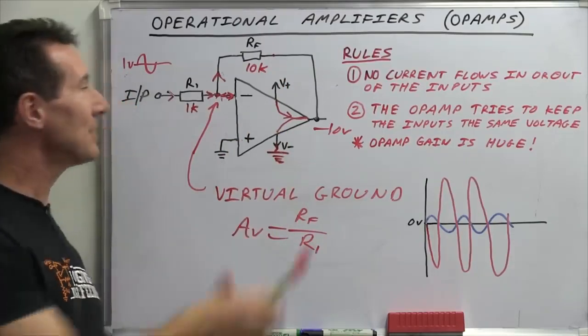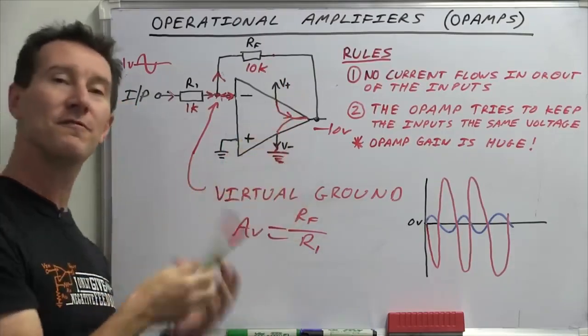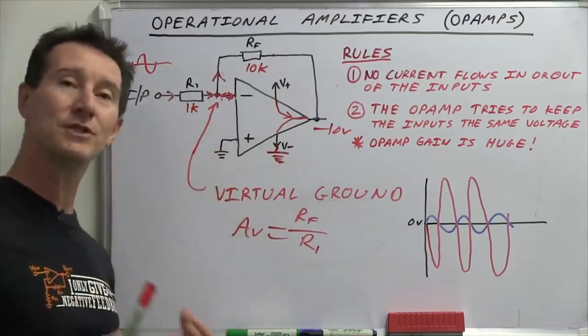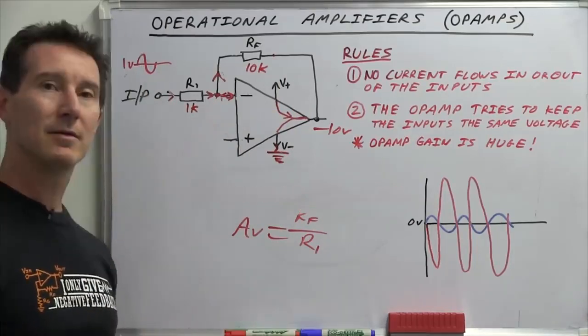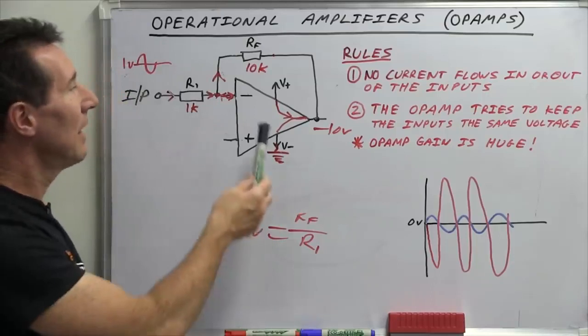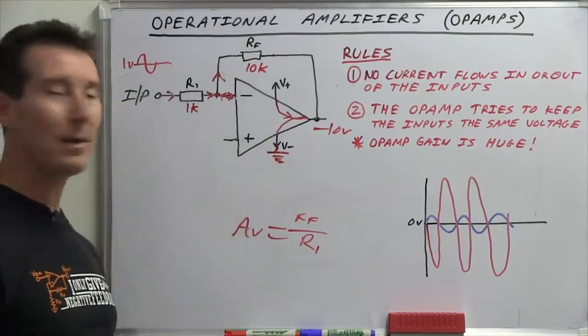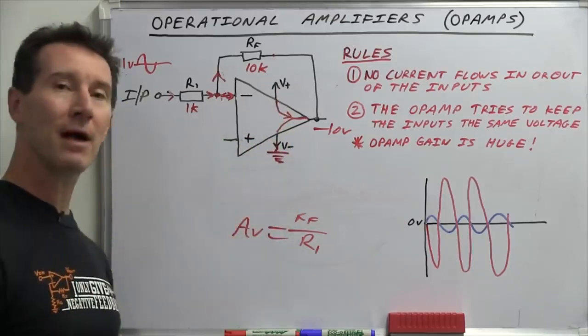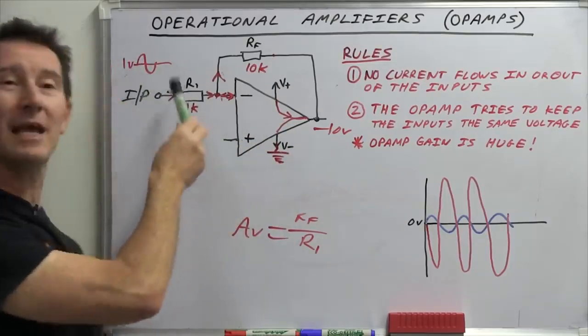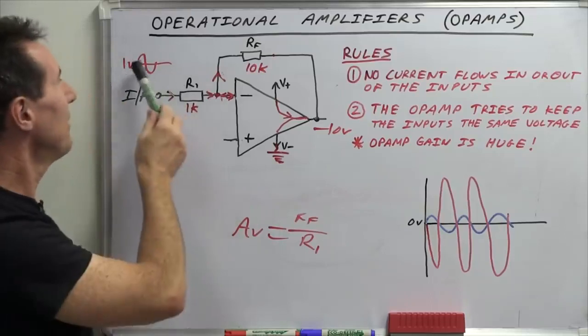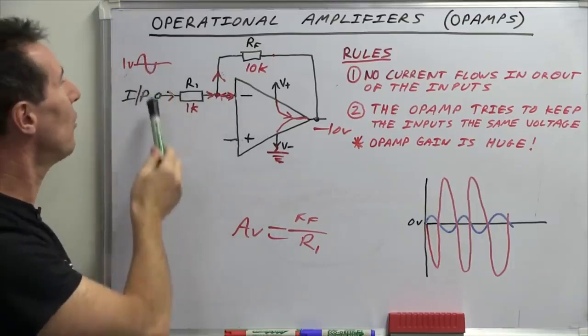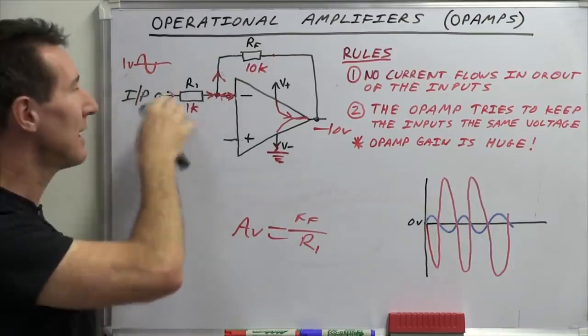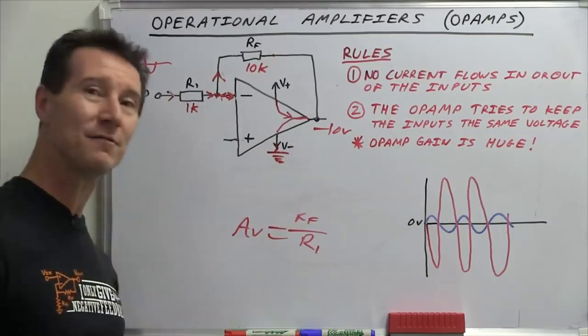So your op amp has to always be powered in the configuration that you expect your input signals to be referenced to. So if we were to use the inverting op amp configuration like this with a single supply rail, and we wanted to amplify AC signals, well, the signals can't go negative like this. They can go negative on the input, but you're never going to get that negative voltage on the output.